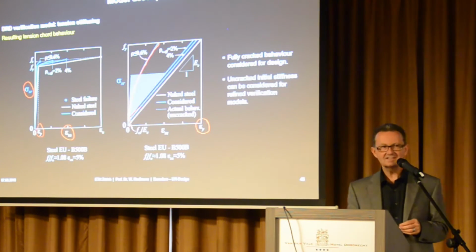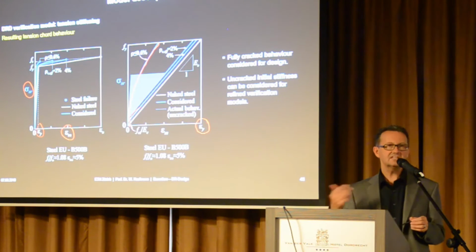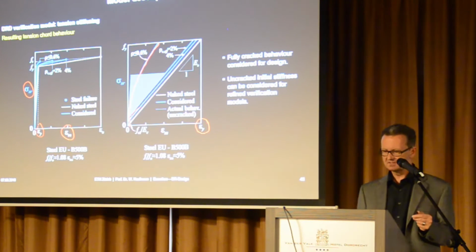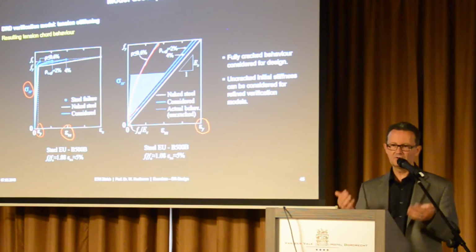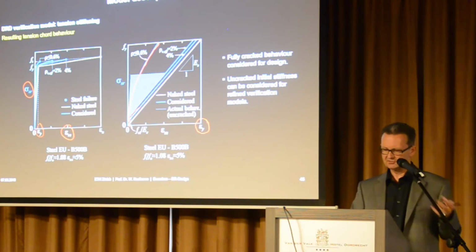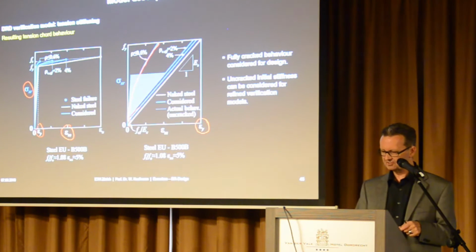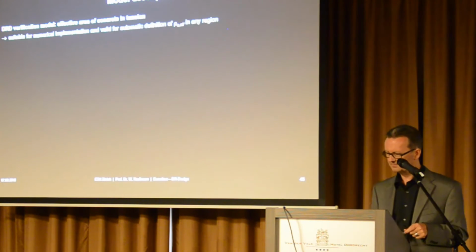And we neglect the initial uncracked behavior. We can activate that for more refined calculation, but it's not recommended usually, because you might always have an initial crack from shrinkage, from other effects, and so on. So in the standard version, it's not that common.